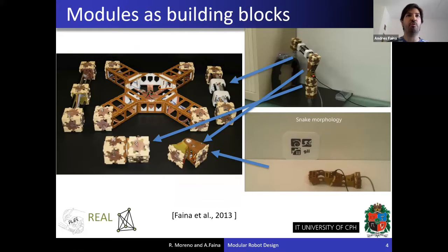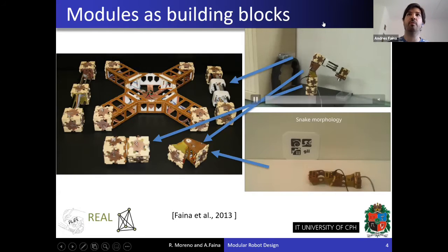And we can also see my previous work. I guess this is a heterogeneous modular set. In this case, we have 4 different kinds of actuators, and we can combine them to perform different tasks. For example, this manipulator here is built with a telescopic prismatic module, a hinge module, and a rotational module. And this is fully functional, I guess. Once we build it, attaching these modules together, we have a functional manipulator, which is able to move some nuts from one place to another, for example.